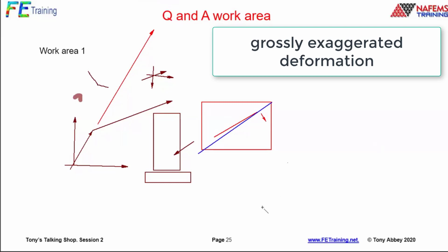The normal modes solution, again, you can exaggerate that. As you go to higher frequencies or higher, more complex mode shapes, the reason I like that is things get busier, and then you tend to zoom in and see these local features because they pop out of the woodwork. Maybe local features which aren't connected together we don't notice overall. The higher order mode is going to pick those up and say, right at this point, I've got a local mode associated with that kind of feature there.